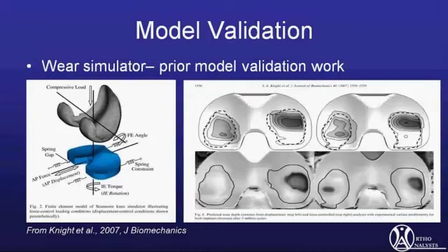In addition to the kinematic performance evaluation, they're also looking at the ability to predict wear. In this case, this particular paper is just using the Archard's law. But it shows that, at least from this qualitative comparison, the wear scar for these two implant components was well represented, both in terms of the locations as well as the relative depths of wear on the medial and lateral components.